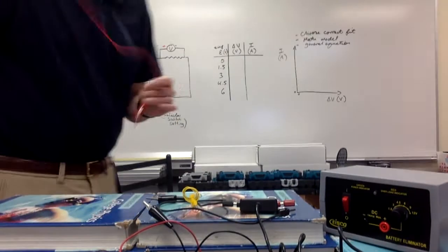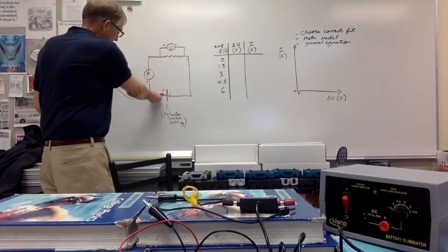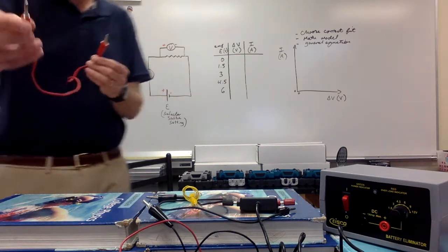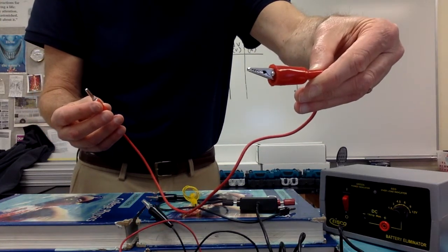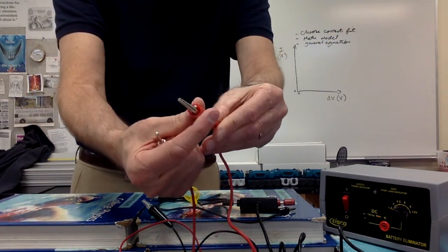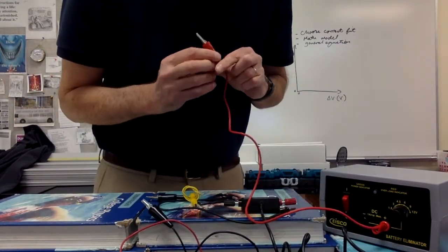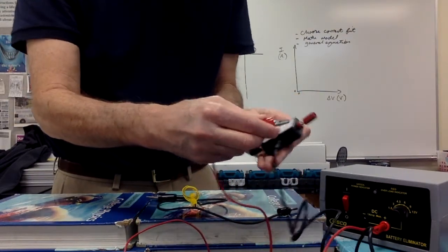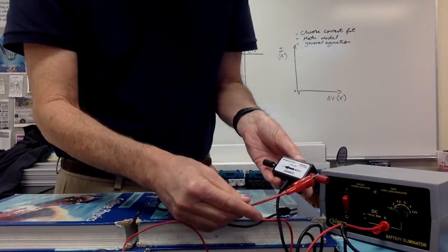All right, so the first thing I'm going to do is plug into the power supply and then into the current probe, the ammeter that measures the current. This is called a banana plug, and this is called an alligator clip, which is appropriate for Xavier gators. I'm going to plug that in here to the red. By the way, polarity matters. You go positive to positive, so I want the positive terminal of the battery to the positive side of the ammeter.